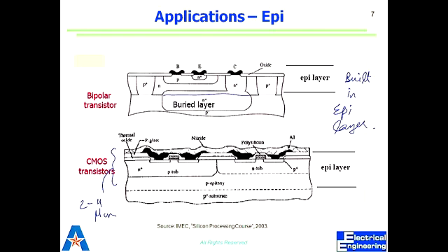Okay. Yeah, because in a MOS, the channel is different from the source and the drain. So you would not want that to be heavily doped because then that would add to the resistance. But the channel is always formed by inversion. So too much background doping is good because now you have much more control over channel formation. It's going to switch off only when you go above threshold. So that's also a benefit of why you want it heavily doped.